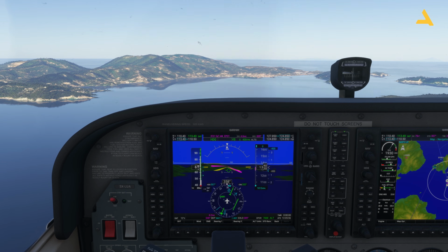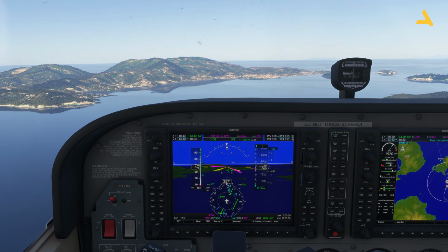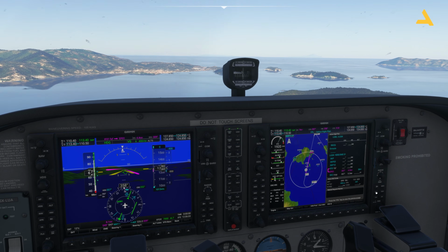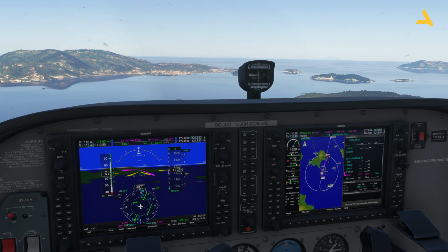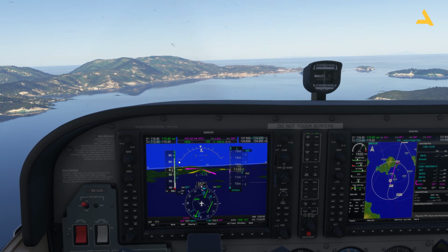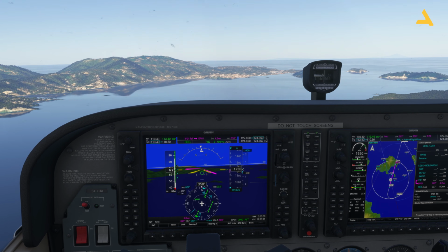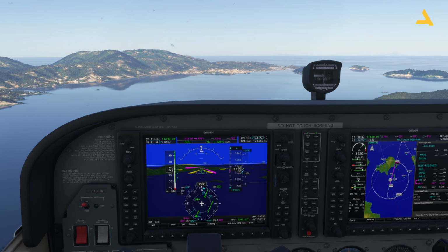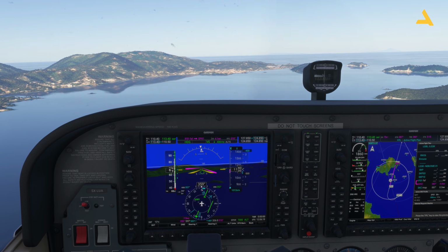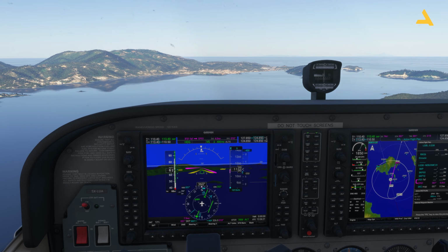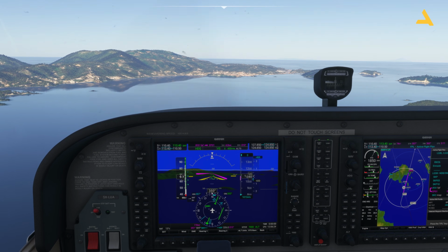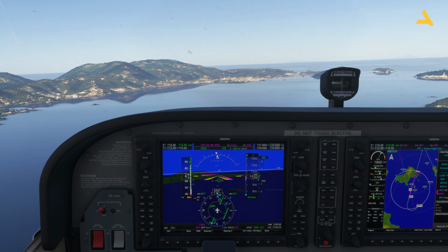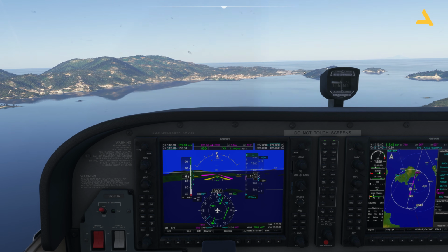The best thing is to first make this flight plan in the G1000 so that you can visually see it. You will see all the speed and altitude constraints and everything. It will help you understand the approach plate better. Once you have an understanding, then you can do the VOR navigation. But for every runway, the approach procedure can be different. So this was for Scathos. If you are doing some other VOR approach, maybe there's no NDB at the runway. Because at this airport, there was an NDB.